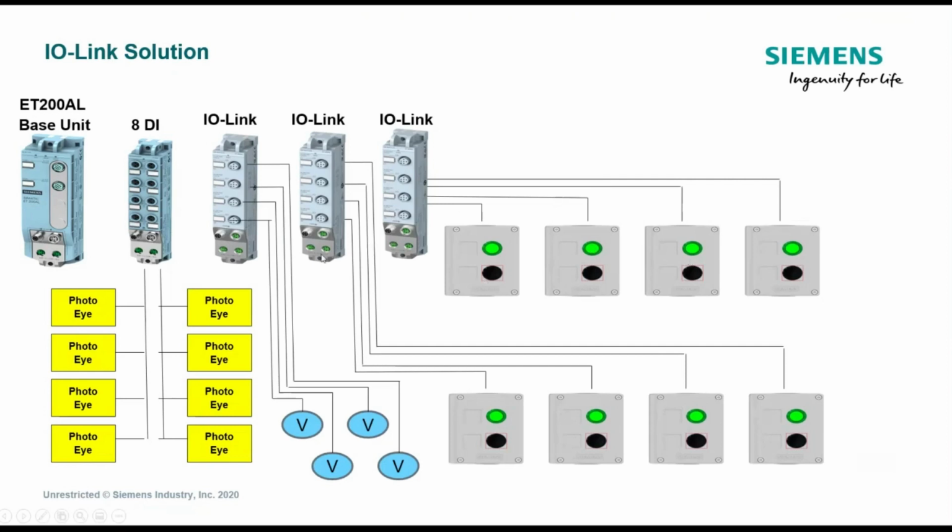So again, it really depends on the master. If it's a slice style, it's to the limit of the digital IO of the PLC system you're playing with. If it's the IP67 format, it's usually anywhere from 4 to 8 devices. Hope that answered the question.